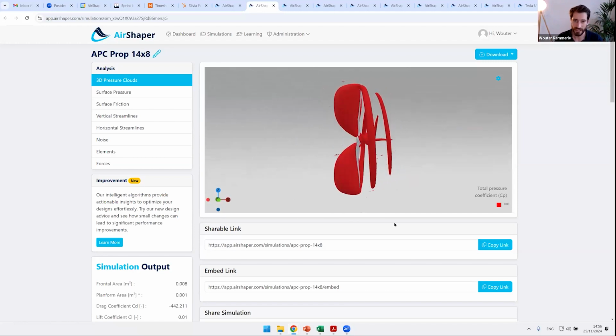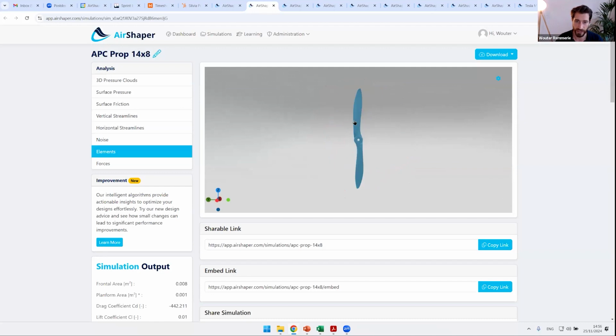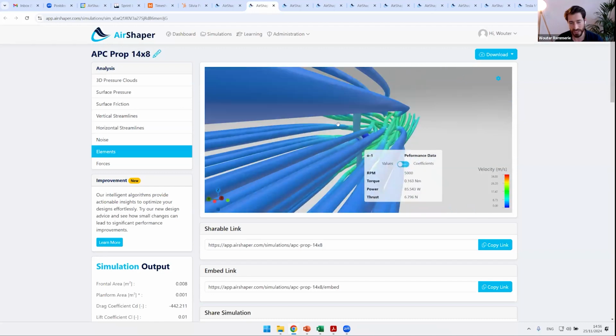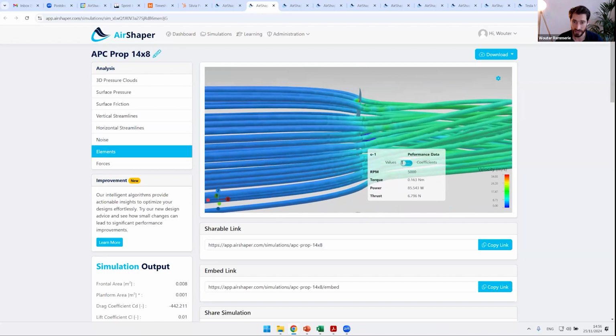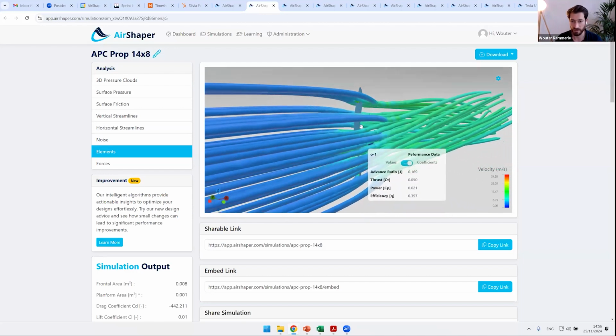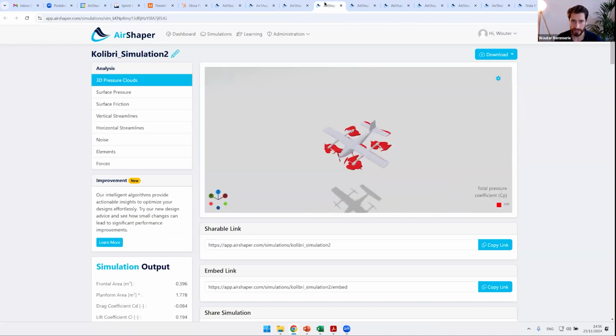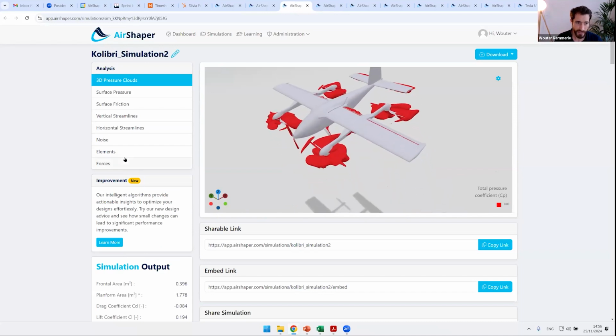And then the size of this domain that you put around it is important. Within that subdomain, you're going to solve extra equations, which take the centripetal forces and the Coriolis forces into account, which allow the software to develop a swirl and calculate the torque and everything. So again, in our case, it's all about automation. We automatically calculate torque, thrust, and the power, and also the propeller coefficients behind this propeller or on this propeller.